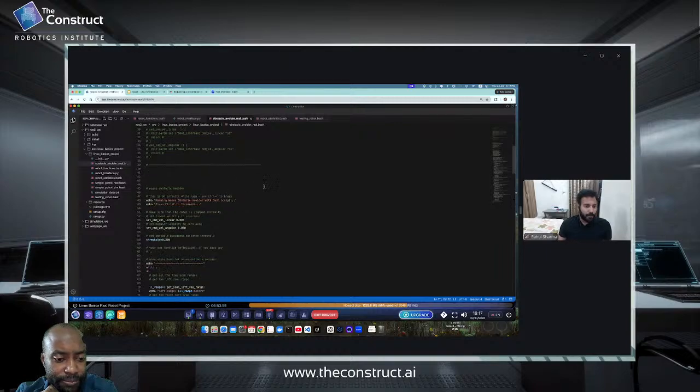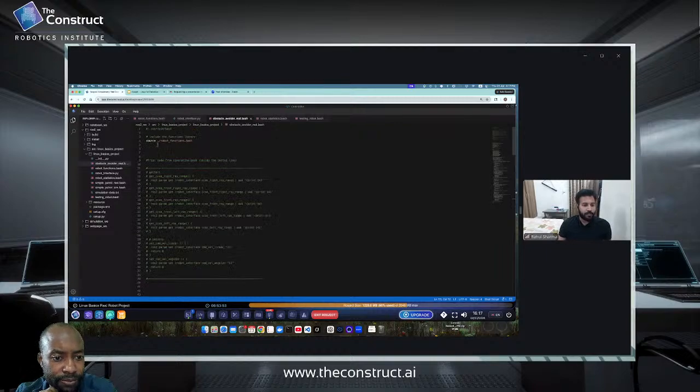Okay. So first of all, the first line is /usr/bin/bash. What it does is it basically tells the terminal that it is a bash script. It's called the shebang line. After that, we have source robot_functions.bash. It sources this file, robot functions, which we saw here.